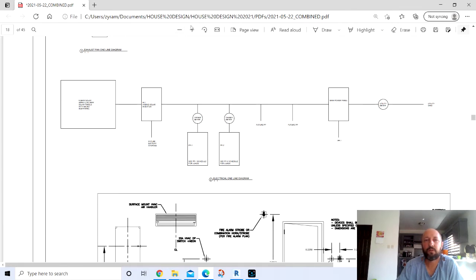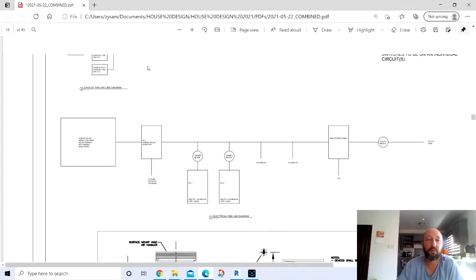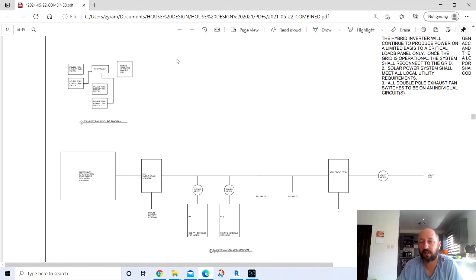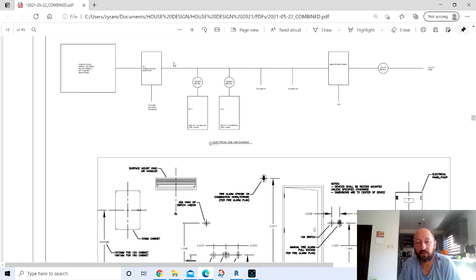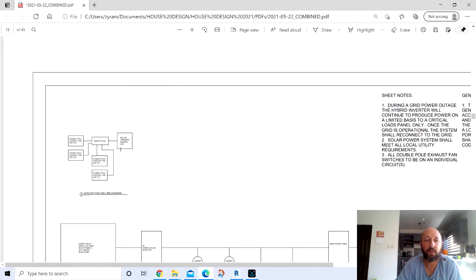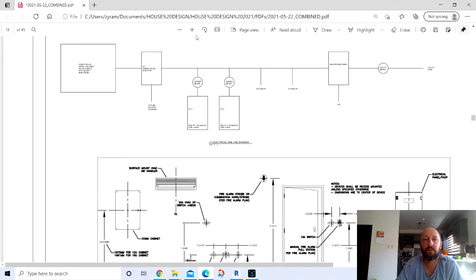I'm curious to see if that'll work. There's other ways to do it. I was just not going to put any damper at all, or just have a backdraft damper, but that won't work. If you have infiltration or exfiltration of your air, if the air's going both ways, it'll only block the air from going out, not from coming in. So when you do your blower door test to test the air tightness of your house, it would fail without a motor operated damper that would keep it closed, unless of course you gagged it or something.